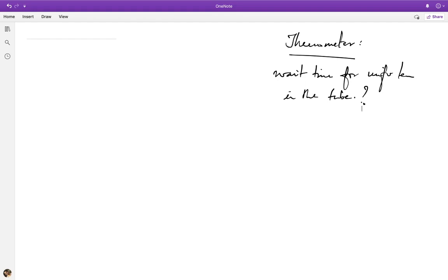So here this is the time scale that it takes for the temperature to become uniform in a relatively thin object, a relatively thin slab. In this case, this is the glass tube. Another similar situation to this is the prototypical case of a heat transfer fin, where we typically neglect the heat transport in the smallest dimension of the film, claiming that it would be uniform much faster than it takes for heat to be transferred in the other directions. So heat transfer fin.